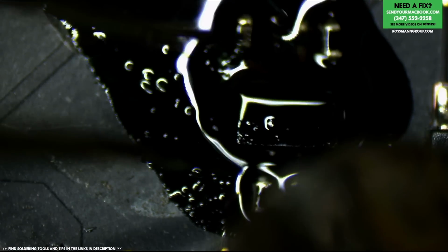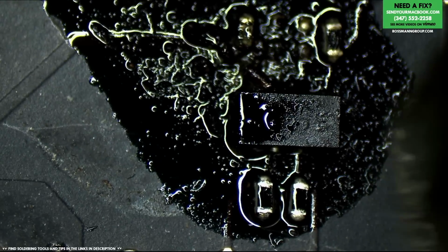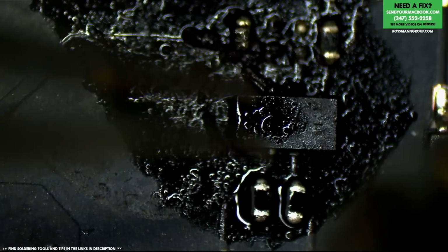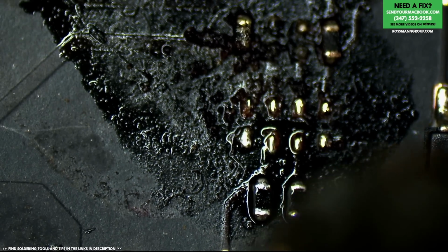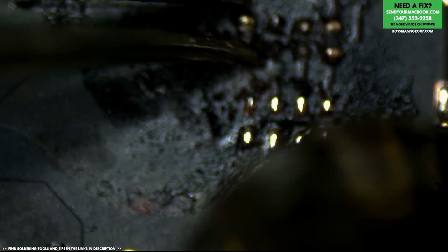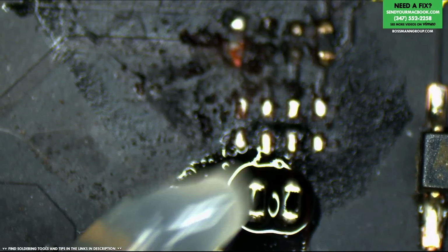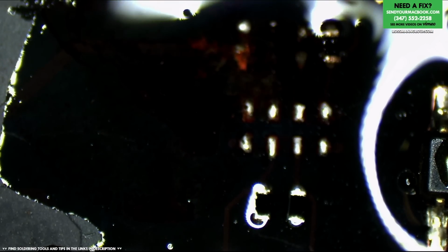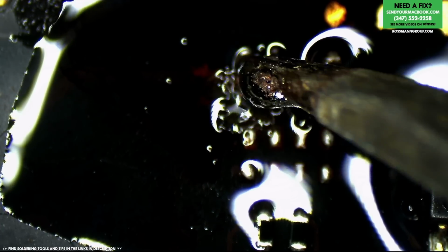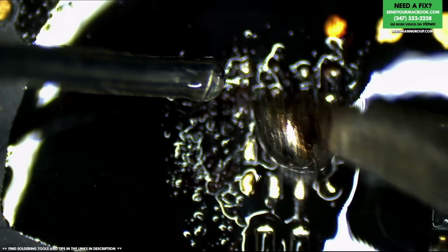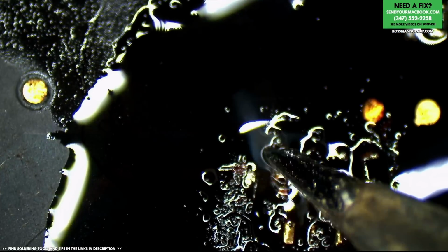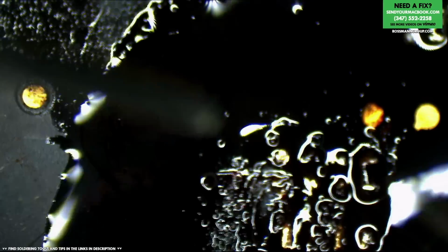All right, so that being said, these are the duck-billed tweezers again. I can't use those for anything. Okay. It looks like I may be missing the PP3V42 via over here. Let's dig a little bit. Might actually be able to scrape it away from right next door.